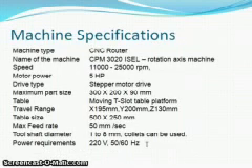And this is the specification of the machine. The machine is called a CNC router, model CPM 3020, with a 300 rotation axis. Its speed is 11,000 to 25,000 RPM, and motor power is 5 HP. The drive is a stepper motor drive. Maximum part size is 300 by 200 by 90 mm, and the table is a moving T slot platform. Travel range is 195 mm in the X direction and 200 mm in the Y direction, and in Z, the spindle moves up to 130 mm height.